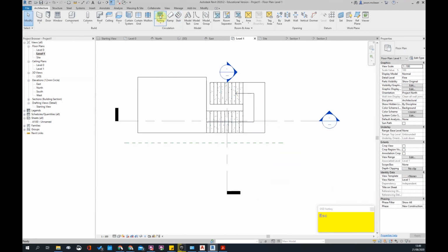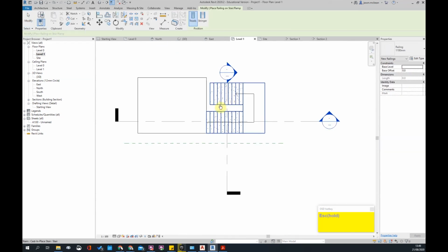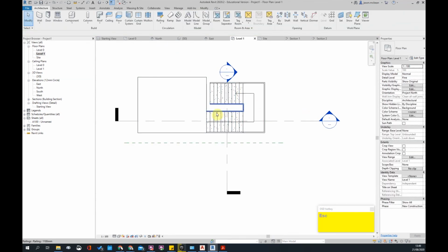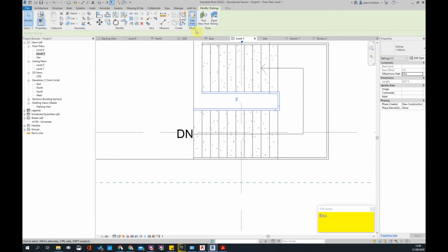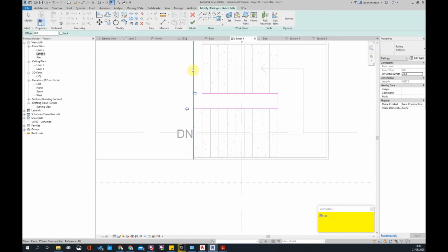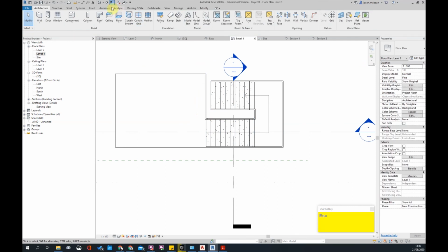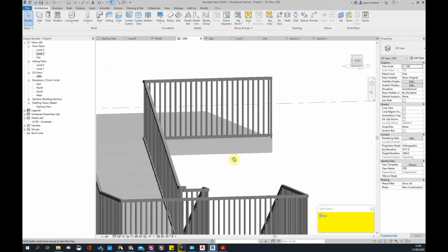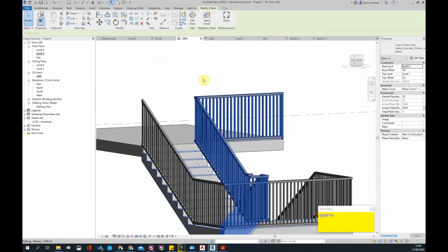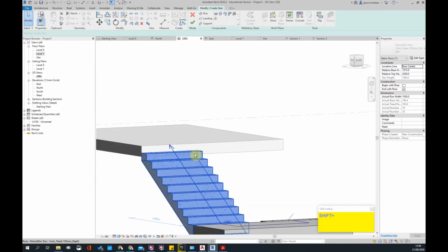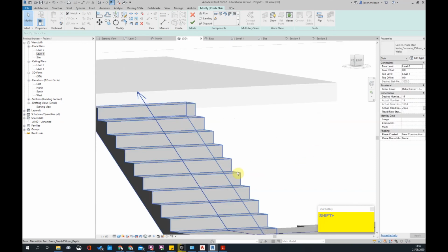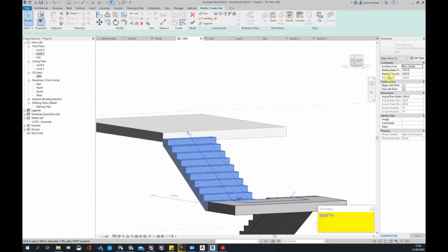Okay, now if I put my handrail, place on step. Then for this inside railing, you just click on it again and say edit path. Then you pick this line over here. Trim these two with that. That's where it ends. And path offset, now the stair will look correct. Okay, so I didn't have to use an offset tool. All I did, in essence, was select this flight of stairs and say it must end with a riser, not begin with a riser. Okay. Actually, I could do that. That should fix it.